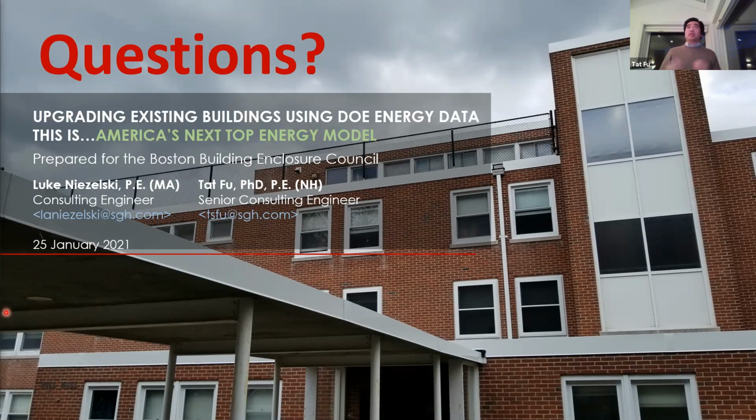So percentage-wise, you're looking at about a 25% increase in cost. However, a triple pane window is more comfortable. So if you have floor-to-ceiling windows that you want to put people next to, you may want triple pane, even though it won't pay back, because it makes that area a more comfortable, usable space, and that will improve your space utilization in your building.